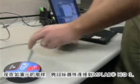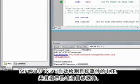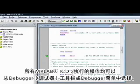Now connect the target device to MPLAB ICD3 as shown. MPLAB ICD3 automatically senses the voltage on the target device and indicates that the target has been connected. All of the operations that MPLAB ICD3 can perform can be selected from the debugger toolbar or the debugger menu.